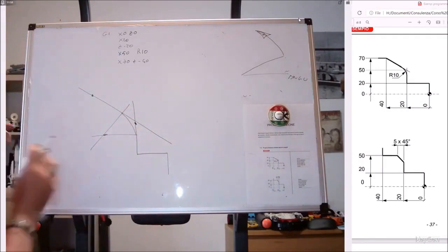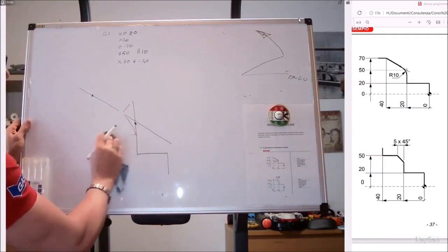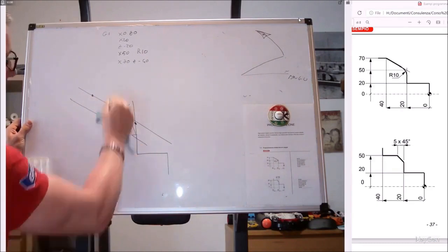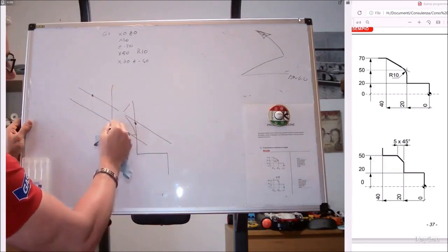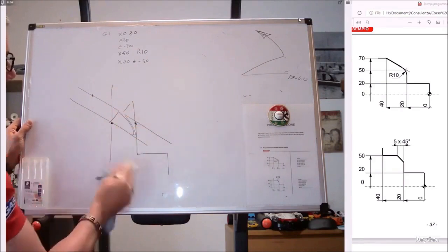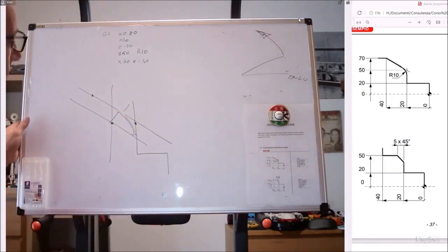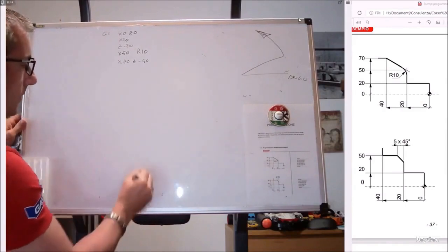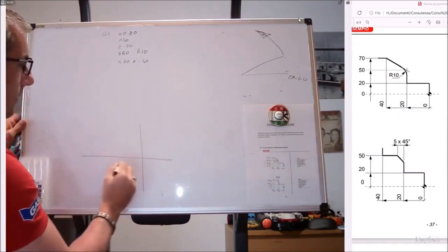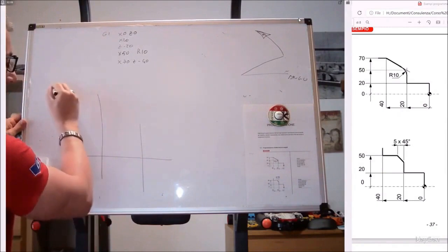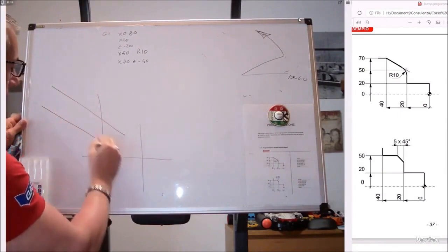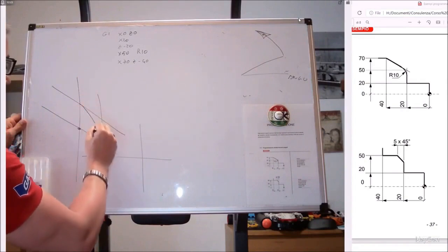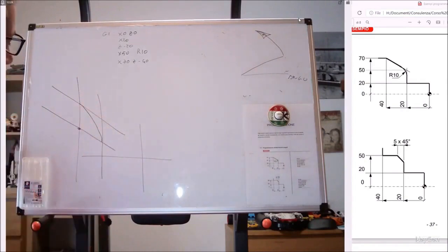Actually, to tell the truth, you would have taken the set square, made a parallel line of 10 millimeters, found the center, and made the radius. My goodness, it turned out terrible, but redo it. If you had a set square in hand, you would have drawn a line parallel to this one, found the center, and with the compass, you would have made the radius.